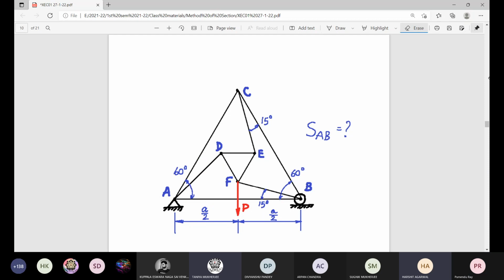Any more good suggestion? Sir, about point B. About point D? B. This one. About point D, there will be two unknowns. This is eliminated. About point B, unknown, unknown. One equation, two unknowns. Can you solve it? Not possible. You can try other options also, but primarily you must understand that a concurrent coplanar force system will not give you a solution for more than two unknowns.